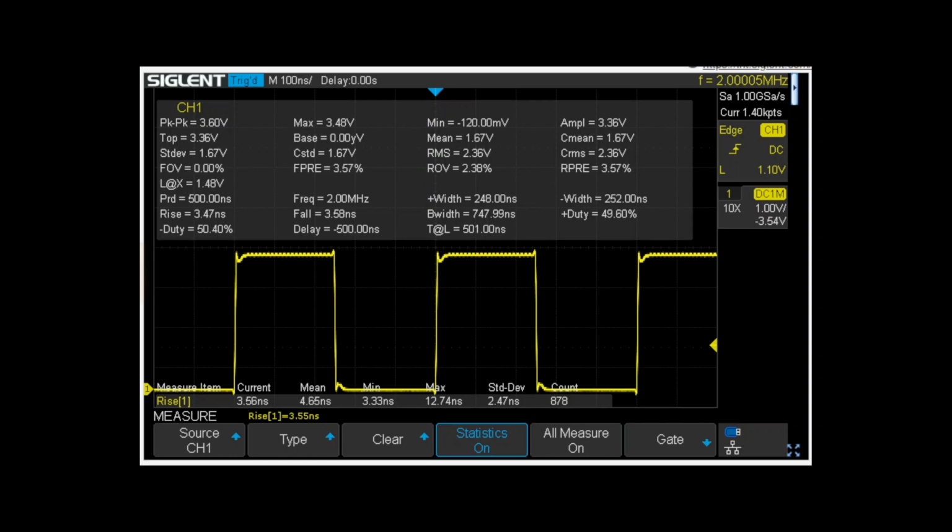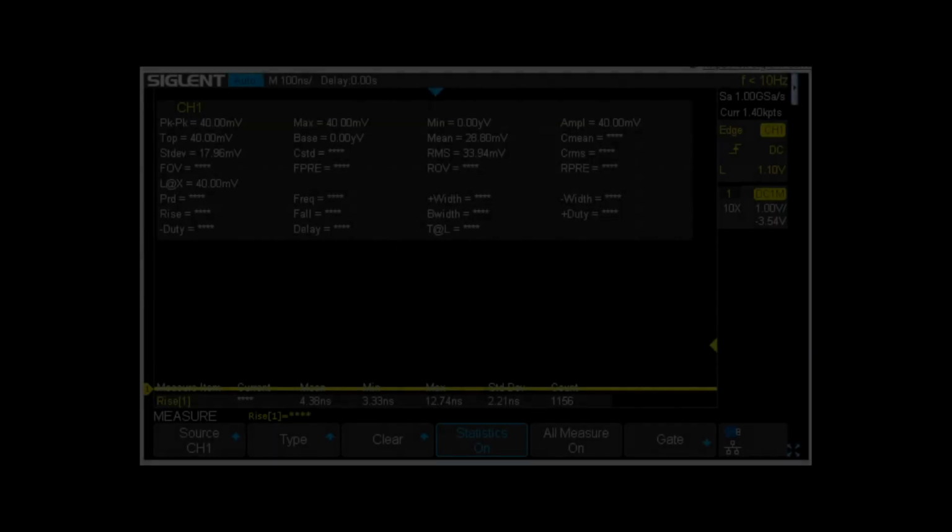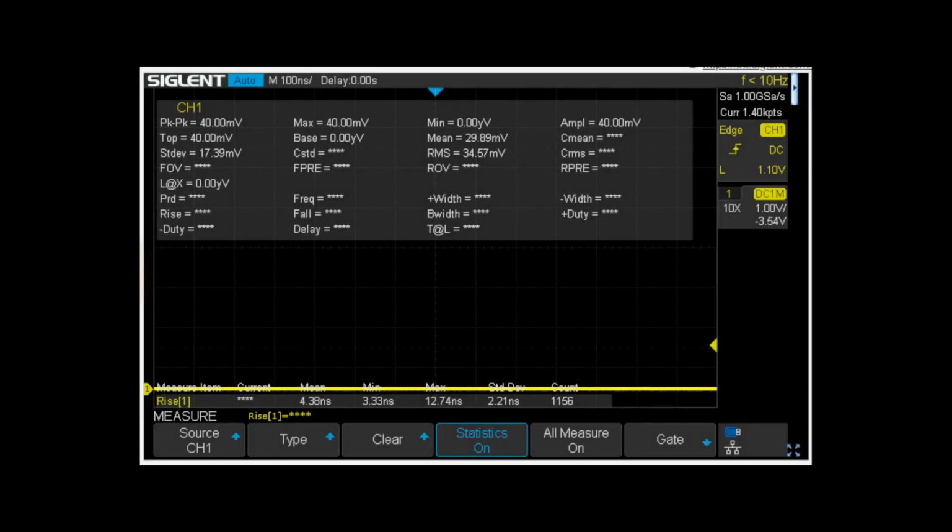This is a 100 megahertz bandwidth oscilloscope. And so the shortest rise time that it should be able to see is around 3.5 nanoseconds. So that suggests that with maximum drive strength, the Raspberry Pi rising edge is no more than 3.5 nanoseconds. Now I've switched the Raspberry Pi drive strength to its smallest value, 2 milliamps, and let's see what we see.